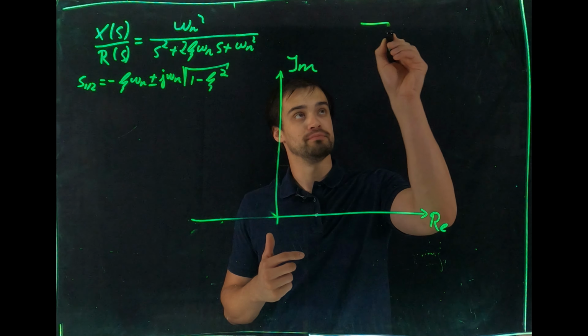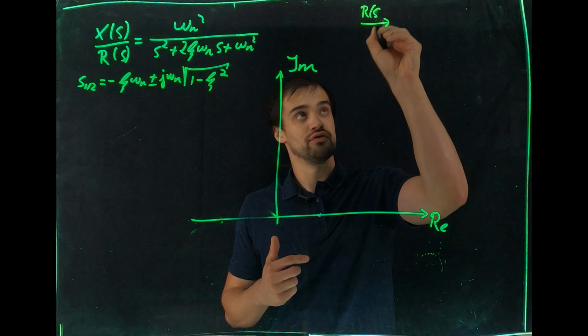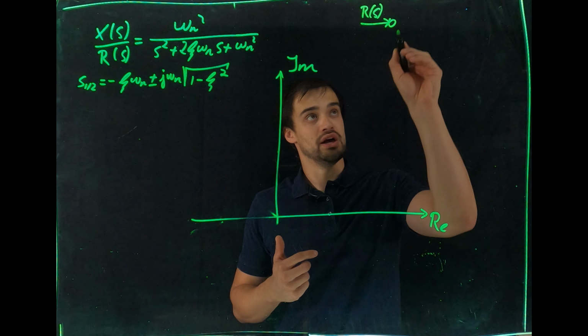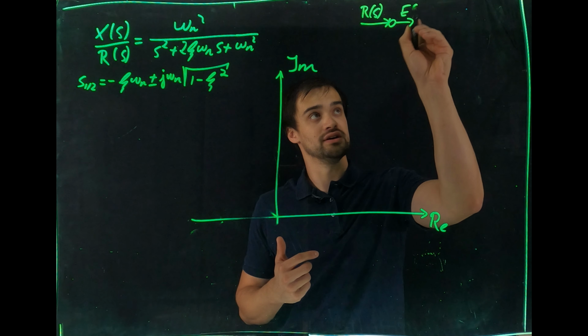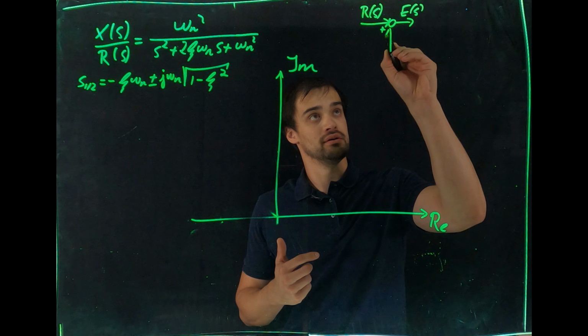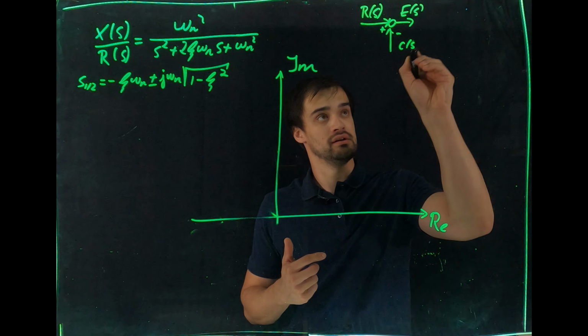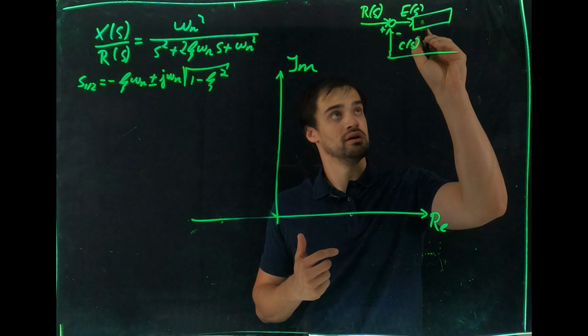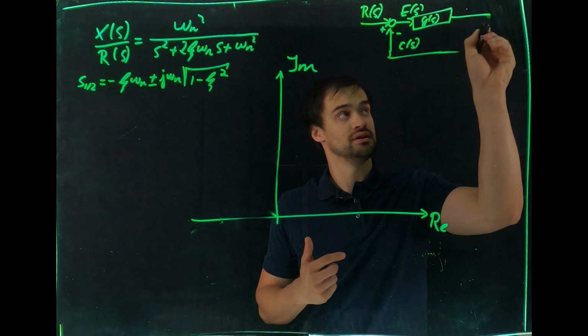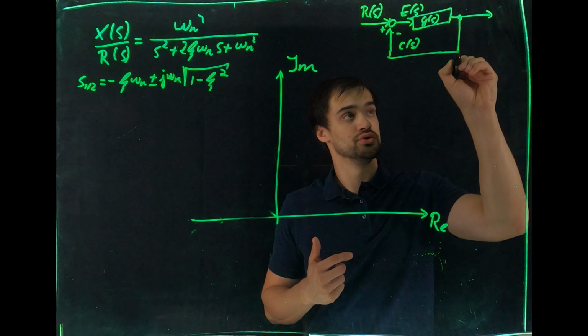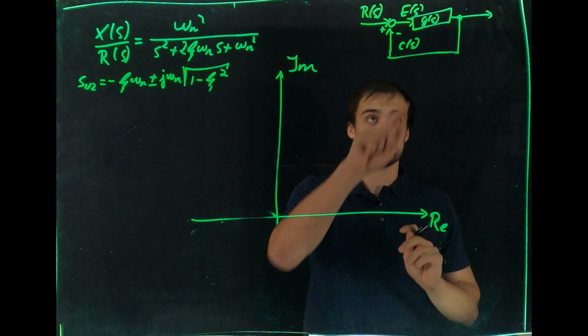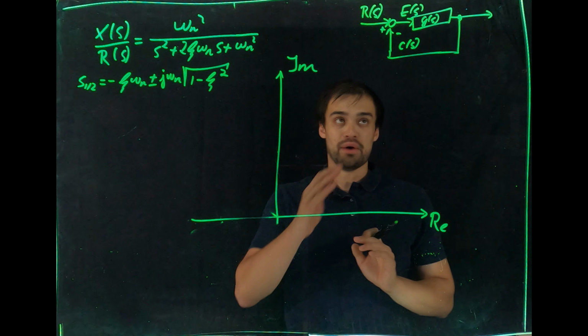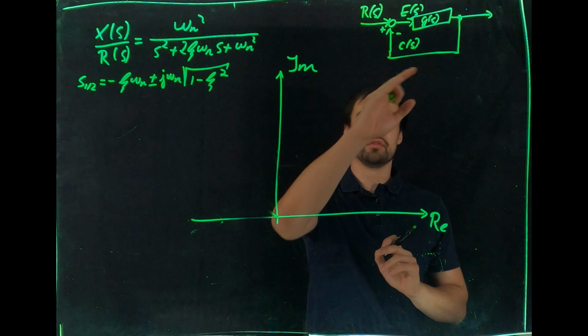Now we're looking at the steady state error of the feedback loop. Now what do I mean by feedback loop? By feedback loop I mean we have an input R(s) with an arrow to E(s) and a feedback C(s), and we're looking at the plant G(s), which goes out here. This is a node, and we have a unity feedback. So H(s) is basically just 1. And I would like to look at the steady state error of this feedback loop.